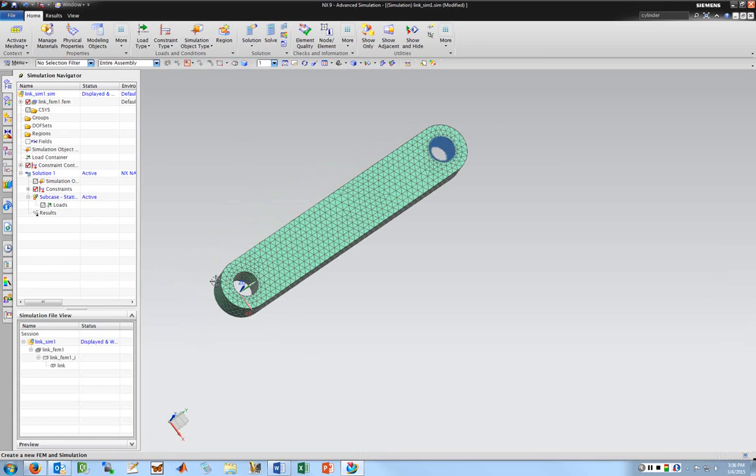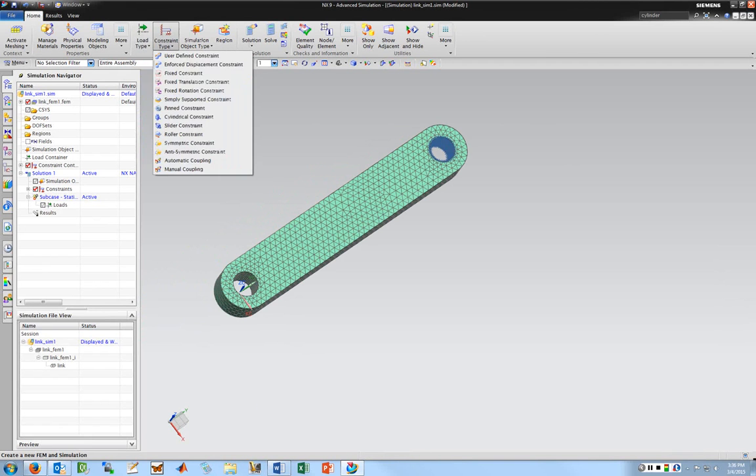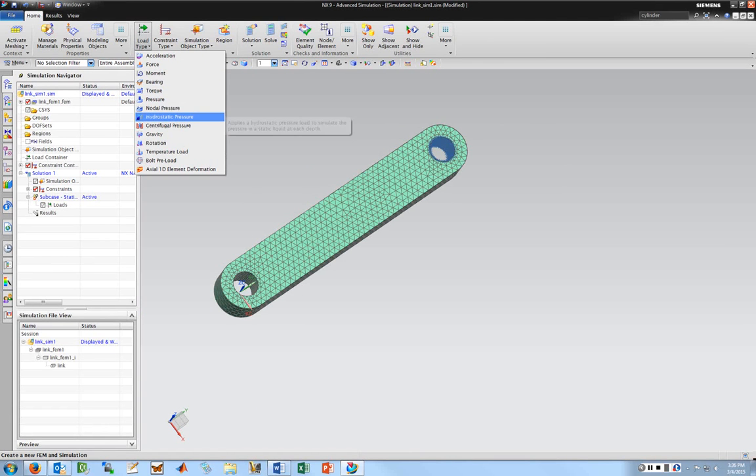Now I want to apply an axial load down here. So I'm going to go up to load type. You can see all the different options you've got here. So all sorts of interesting stuff. You can see the temperature load if you're doing a thermal, and if you want to mess with a thermal. Hydrostatic nodes, a pressure if you've got a pressure, like if something is a pressure vessel, something like that. Torques, bearing, again, that might be useful for applying loads that are more realistic for things like bolts, or gears or cams or things like that.